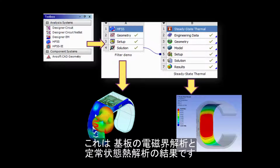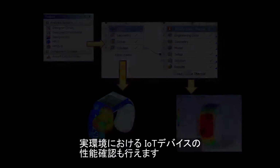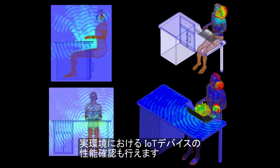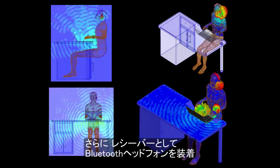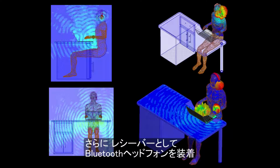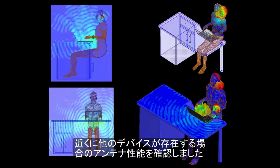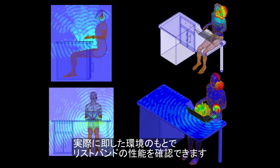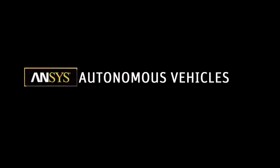Here you see an electromagnetic analysis of the board coupled to steady-state thermal analysis to ensure that excessive heating is avoided. What's more, you can test the performance of your IoT device in a realistic environment. Here you see the wristband added to a human body model. A Bluetooth speaker was also added to model a receiver and the performance of the antenna in the vicinity of other electronic devices. The simulation includes the entire room to test the performance of the wristband under realistic electronic environments.